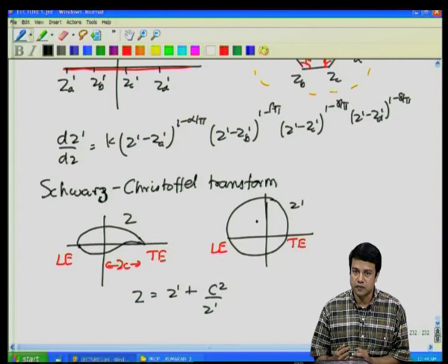One is a sphere moving at constant velocity. We got the velocity field around the sphere. We found that for constant velocity the net force is 0. If the sphere is accelerating, the net force has to be equal to the added mass times the acceleration. For a sphere, added mass is equal to 1/2 the mass of fluid displaced by the sphere. At constant velocity, all components of the force are 0.